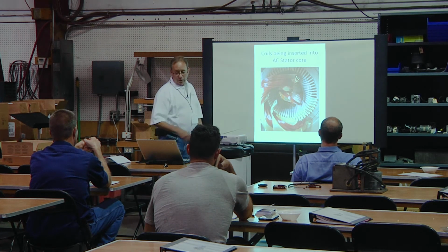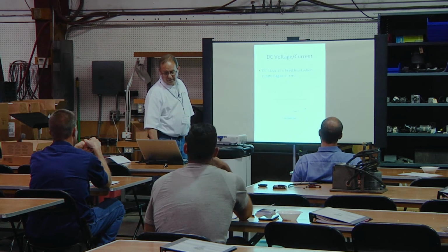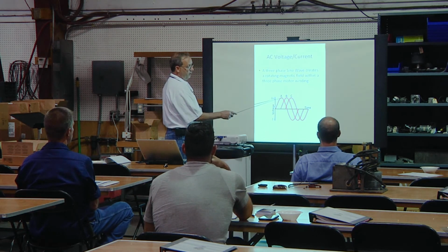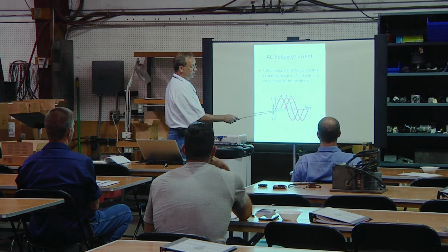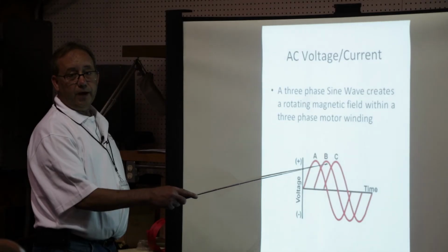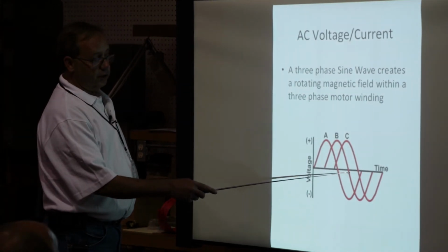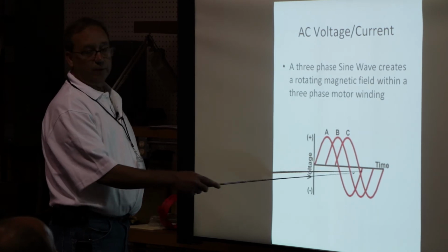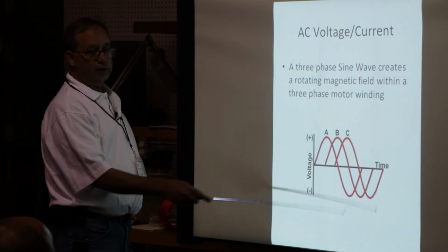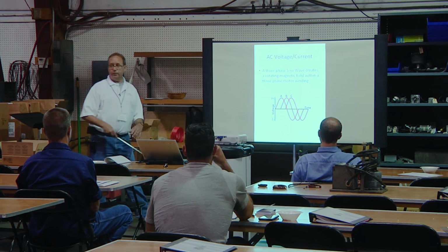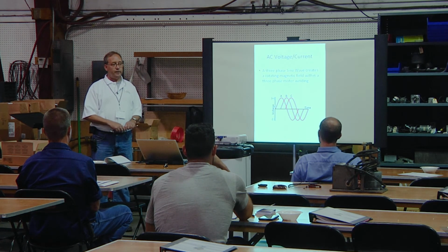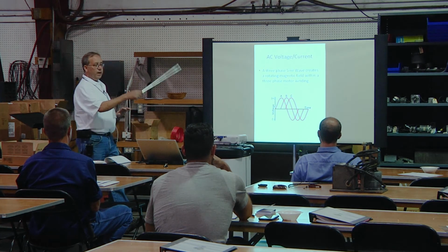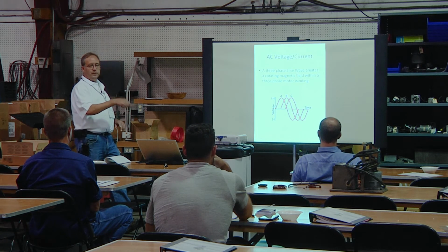And if we go all the way back to our sine wave, as A phase reaches peak positive and starts to fall to 0, B phase is at peak, and as it's fallen to 0, C phase is at its peak, and then they go opposite polarity. So this will go north, south, and if you're running it straight across the line, at 60 times a second that happens. So what it does is it creates a rotating magnetic field that is just chasing itself in a circle.